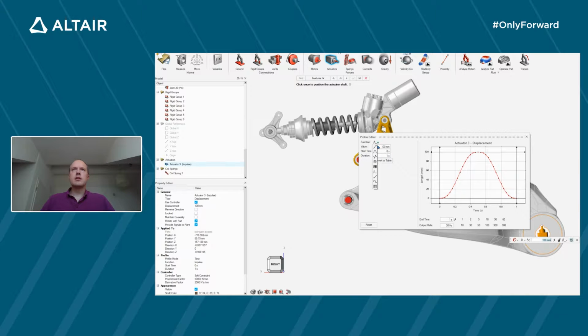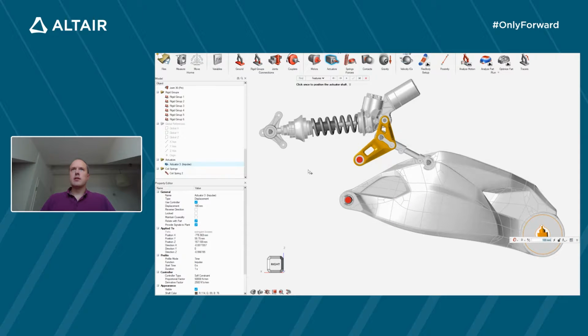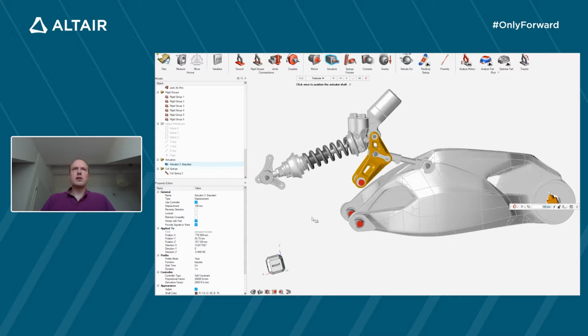So there are different events available, or you can also input user-defined events, for example, like the bumpy road event that I showed in the video in the presentation earlier. So in that case, let's stay with the actuator that will create a displacement of 100 millimeters on the selected surface. And from there, we can run and start the multi-body simulation.